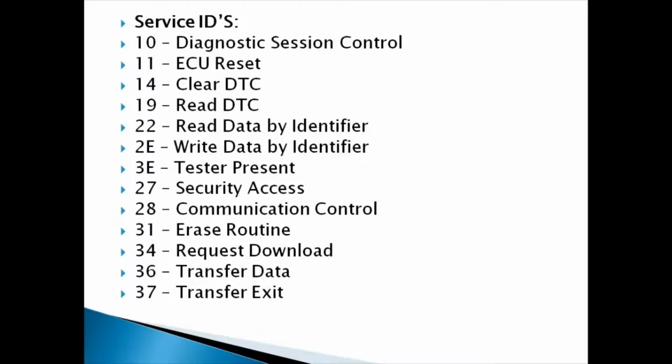These are the different service IDs in diagnostics. We have so many service IDs, but mainly we use these. This is one of the service IDs. This 10 is nothing but diagnostic session control. It will control the different sessions. In diagnostic session also, we have some subsessions. I will tell you here. These are the main service IDs: 10, 11, 14, 19, 22, 2E, 3E, 27.